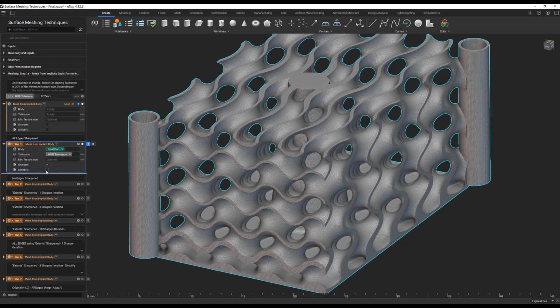You also notice a simplify option. I, again, never use this. This will forcibly decimate the mesh by around 90%, regardless of preserving geometric fidelity. In most cases, when we're trying to mesh an object with a complex lattice structure, the maximum number of elements are going to be on the struts or the lattice itself.